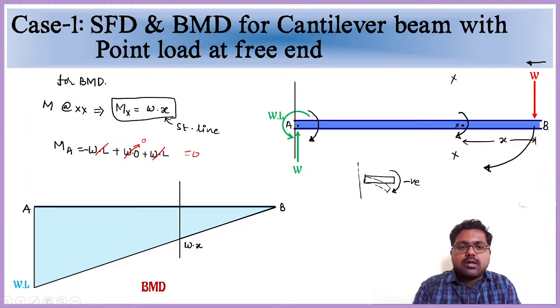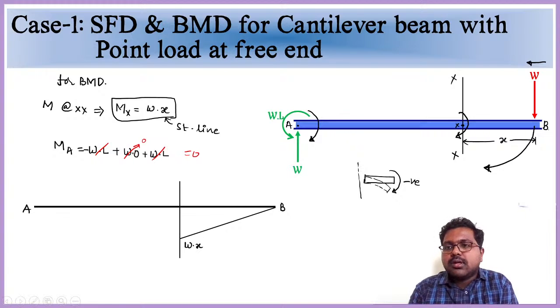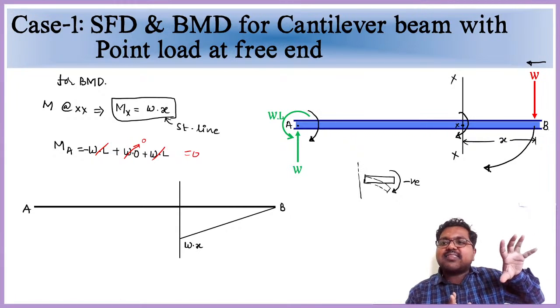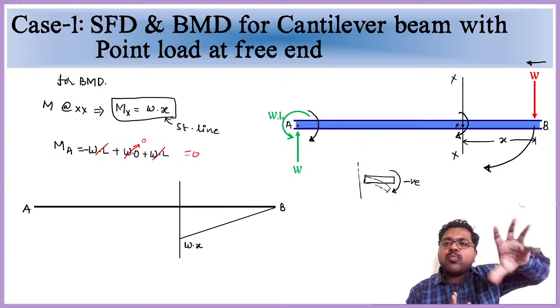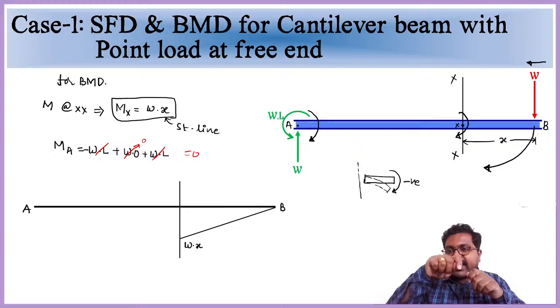See, here I am taking a section XX. When I am taking a section XX here, then at section XX, what is the bending moment acting that we are considering? Okay, I'll just go back. See, at this section XX, on the right hand side, whatever forces are acting, those forces will cause moment in the section XX.